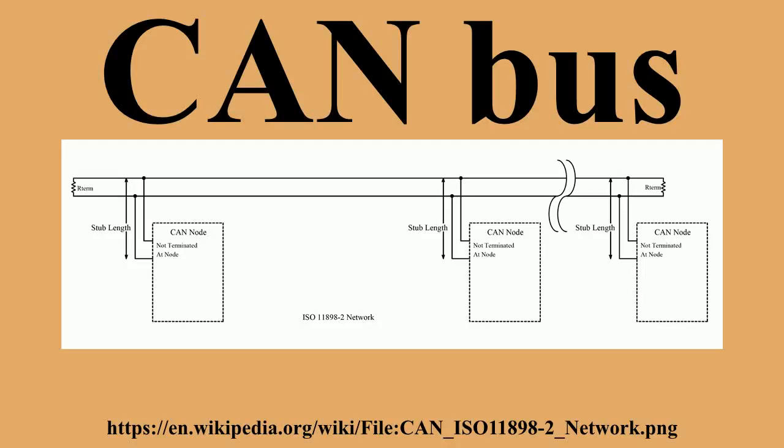High-speed CAN is usually used in automotive and industrial applications where the bus runs from one end of the environment to the other. Fault-tolerant CAN is often used where groups of nodes need to be connected together. The ISO specifications require the bus be kept within a minimum and maximum common mode bus voltage, but do not define how to keep the bus within this range.